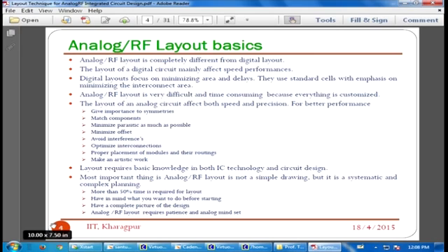That's why it's difficult. And the next thing is, suppose your total time required from schematic to layout is 100%, minimum you have to give around 50 to 60% to layout, otherwise it is not possible. Because in that 60% you have to think how to do it, how to place the blocks. In industry people are fighting for one femto, that is very important. In high speed design, that means 5 gigahertz or 10 gigahertz, it's very difficult. Even one femtofarad can kill your circuit.